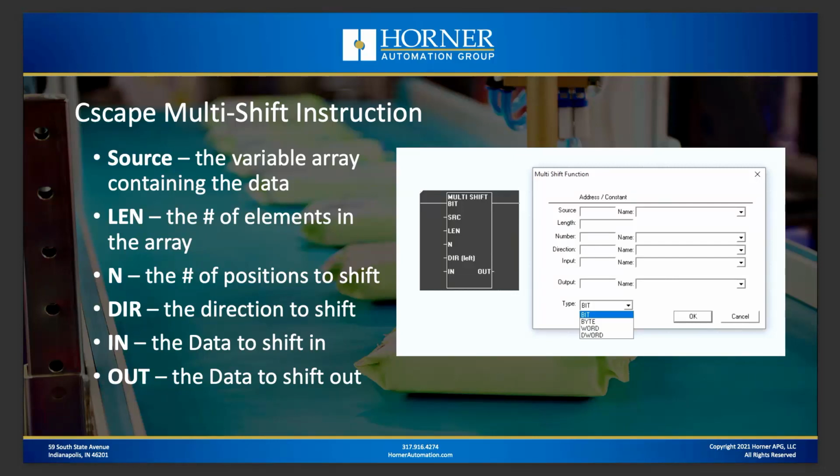The direction parameter basically determines which direction you shift. Are you going to be shifting the data to the left or to the right? When we say left and right, that's where people can get confused, and it's understandable. So the way I like to illustrate it is like this. Think of the binary representation of a word value. When you shift left, you're shifting from lower significance to higher significance, or least significant bits up to a higher significant location. When you shift right, you're doing the opposite. You're shifting from a more significant location to a less significant location.